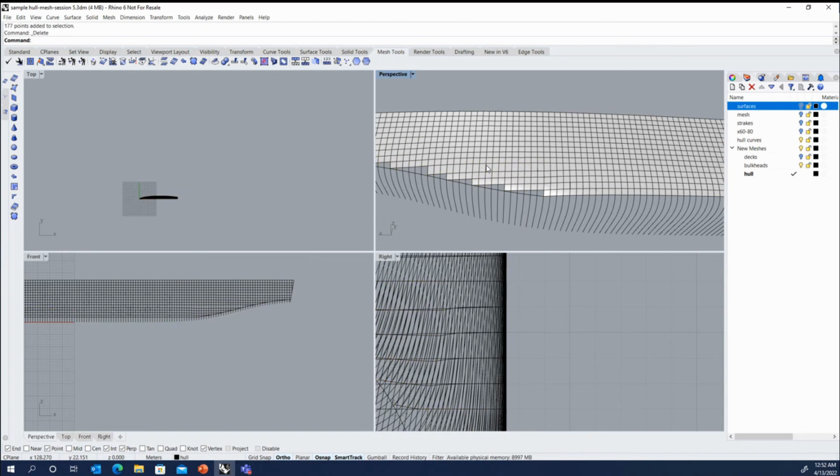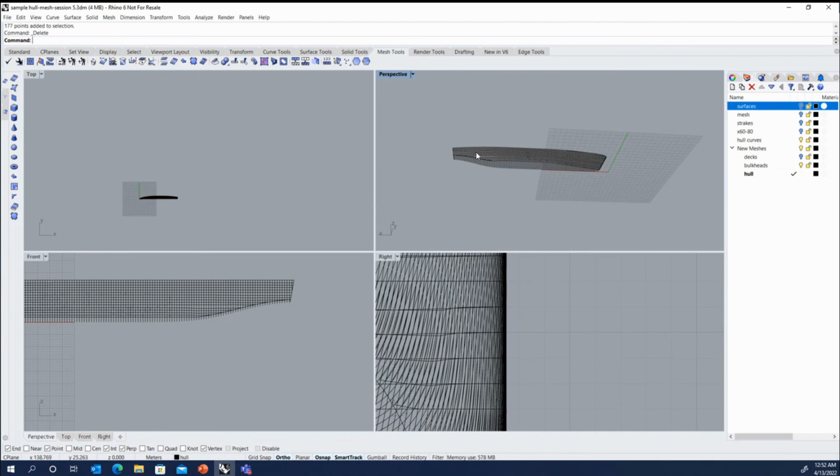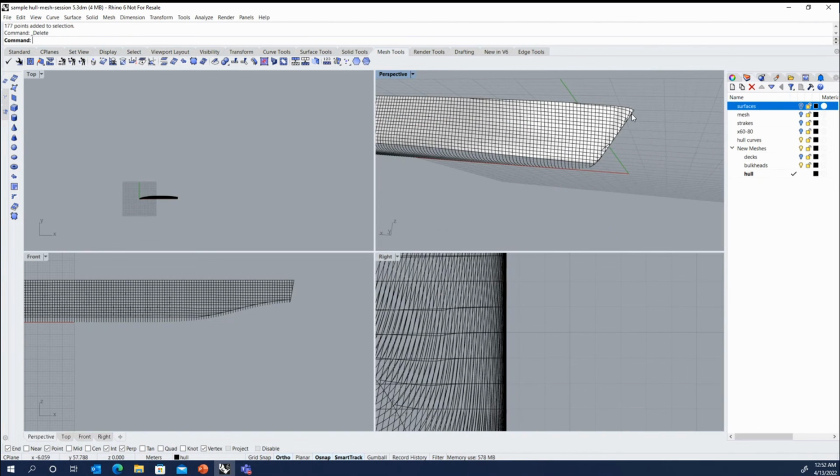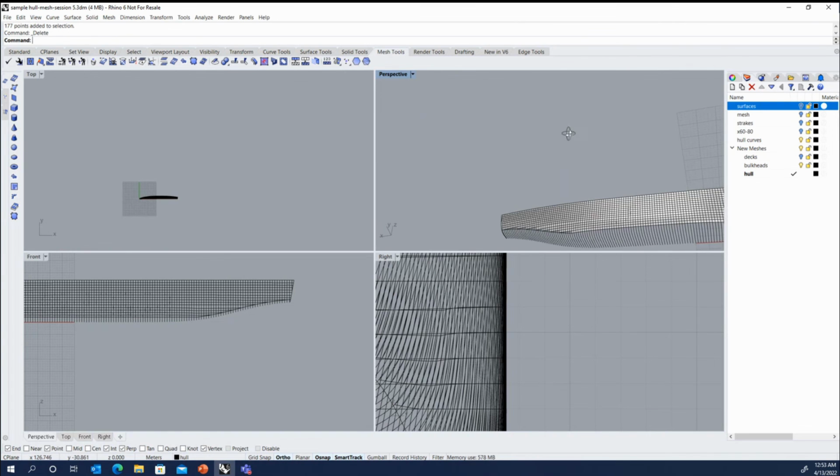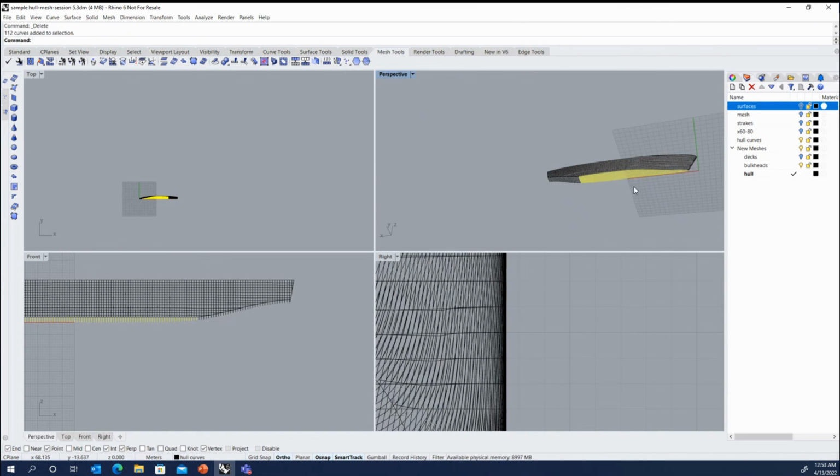If you don't, and you just have the paper expansion drawing, unless you know exactly how that expansion drawing was created, it can be a little difficult to map back onto a 3D model, especially up in the bow region where if you have any tumble home or if you have a fairly rounded bow, if it's very sharp, it'll expand a little better in the drawing. But you can get a lot of distortion in the expansion drawing if you have a bow that's very flat. We have most of the hull done there.